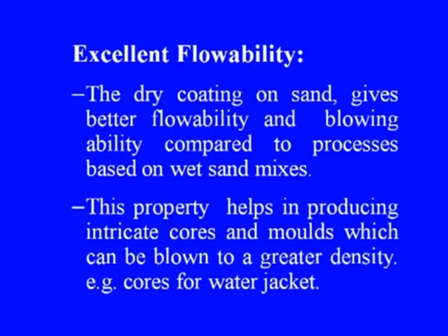Excellent flowability is another advantage of the process. The dry coating on sand gives better flowability and blowing ability compared to processes based on wet sand mixes. This property helps in producing intricate cores and molds which can be blown to a greater density, for example, cores for water jacket.